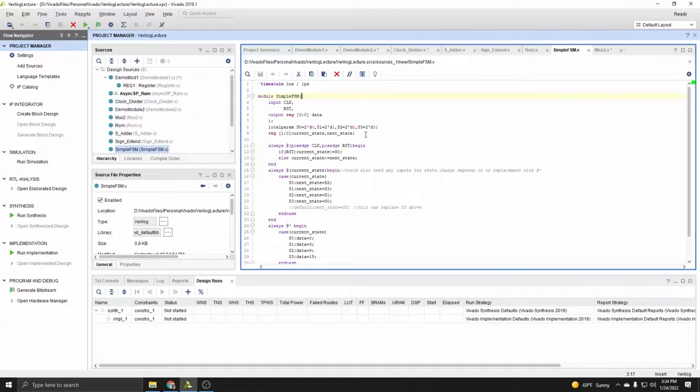Now, before we can really start going into the nitty-gritty of Verilog, you need to really understand your combinational versus your sequential logic. Your combinational is just your simple logic and decisions, and your sequential is your memories, your time delays, and things like registers, flip-flops, latches, memories. Those two things have various effects on how you write the Verilog code.